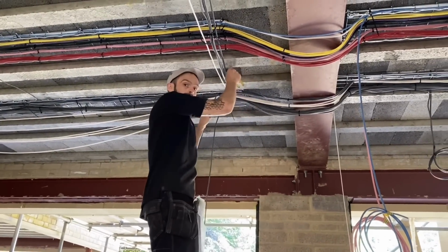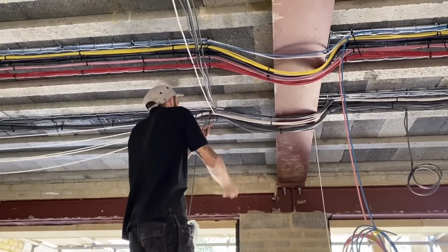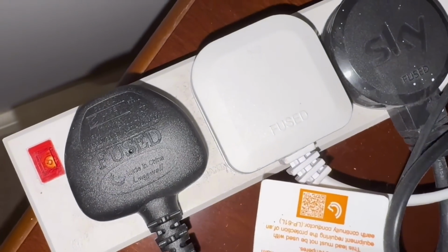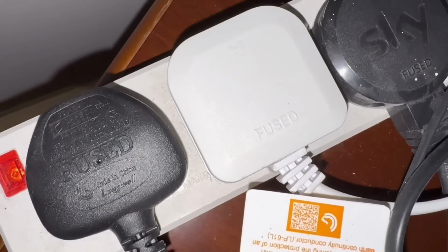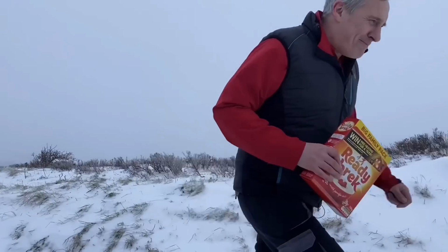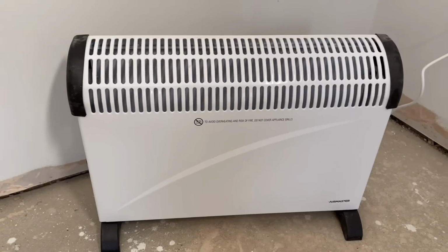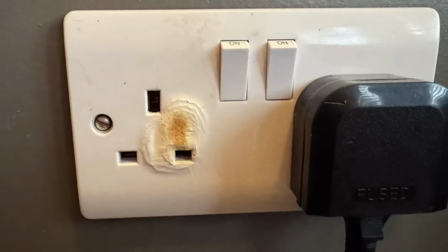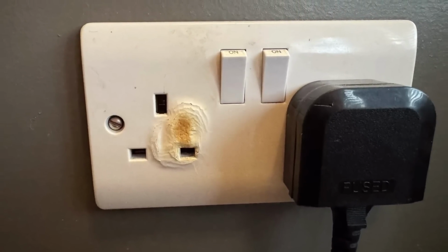The circuits that are more likely to be at risk here are ones where loads can be added by people without electrical knowledge. A good example is a socket circuit. Let's say there's a cold snap and someone starts connecting loads of electric heaters to stay toasty. It may well get to the point where the number of heaters connected causes so much current to flow that the conductors feeding the sockets will start to overheat, leading to the problems already mentioned. The circuit has too much load connected.